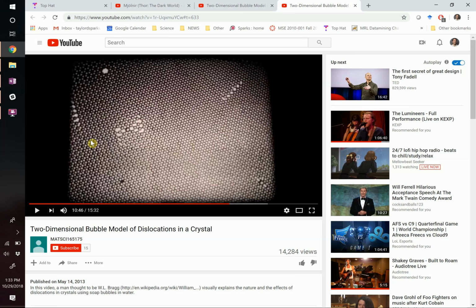Okay? Now, there is the possibility that impurities can move in a material. Next chapter will be all about that. It's called diffusion. But that is way slower than these things move. Dislocations move at like the speed of sound, really, really fast through your material. Atoms hop through your lattice really slowly. So if that's a copper atom in a silver lattice, it's basically stuck there. It's not moving, so your dislocations are stuck there with it.